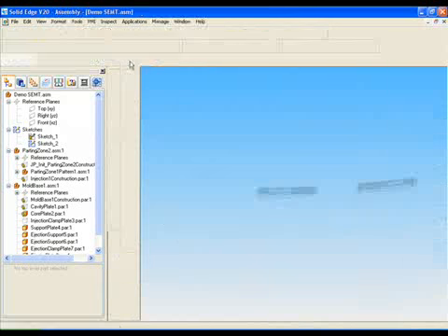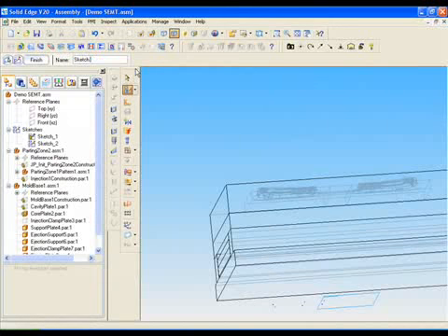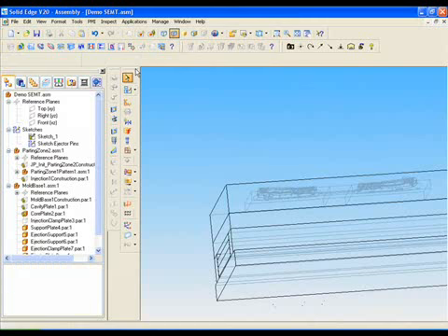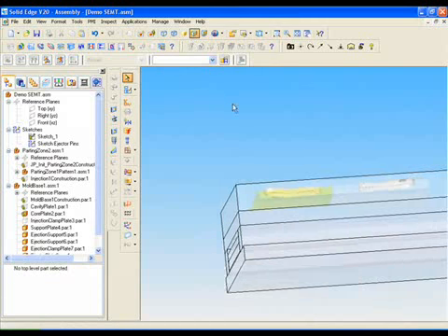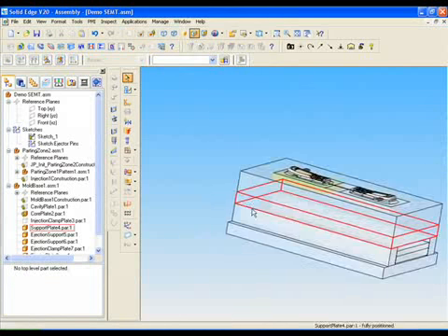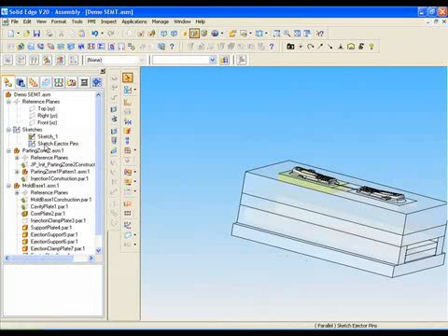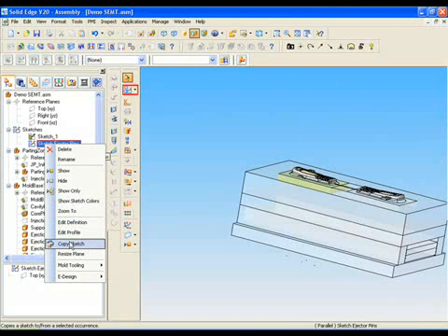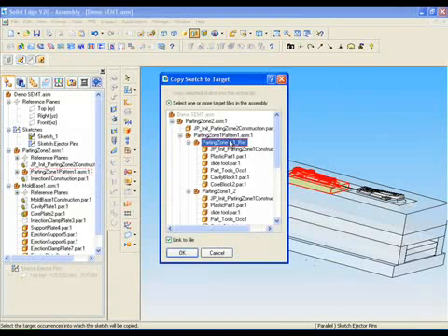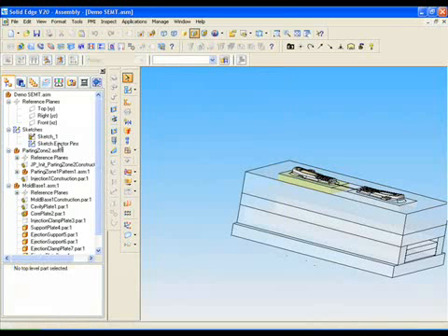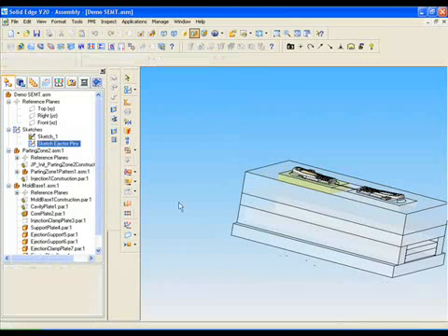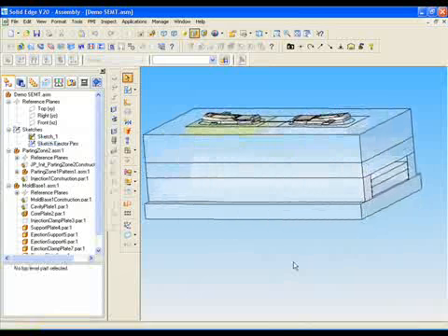We'll now finish the sketch creation and rename it according to its purpose so it's easier to find when needed. The sketch was created at the top level assembly, but we have a pattern of insert parting zones, so if we want to have the ejector pins in both instances, we must copy it into the reference parting zone assembly, as the other instance is only a copy of the reference one.